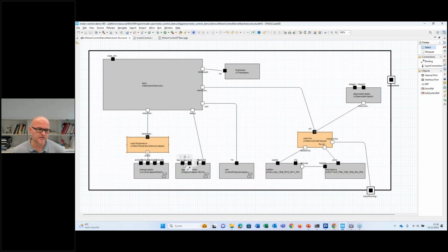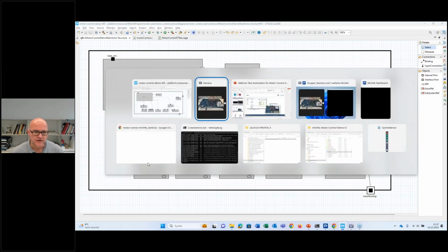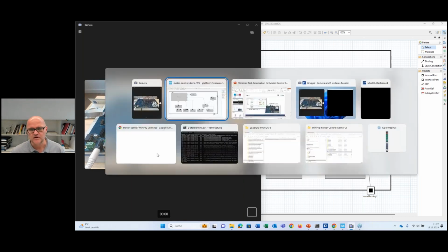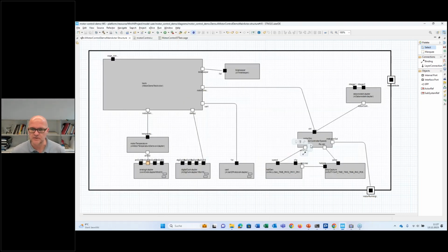And here you have the simulation level. Temperature simulation is pretty straightforward. Celsius in, analog value out, 3.3 or 5 volt analog values. Here you can see that's the analog port 1. That's basically this red cable here. Here we have 16 analog outputs to stimulate the motors, for example. And here we have the motor simulation.